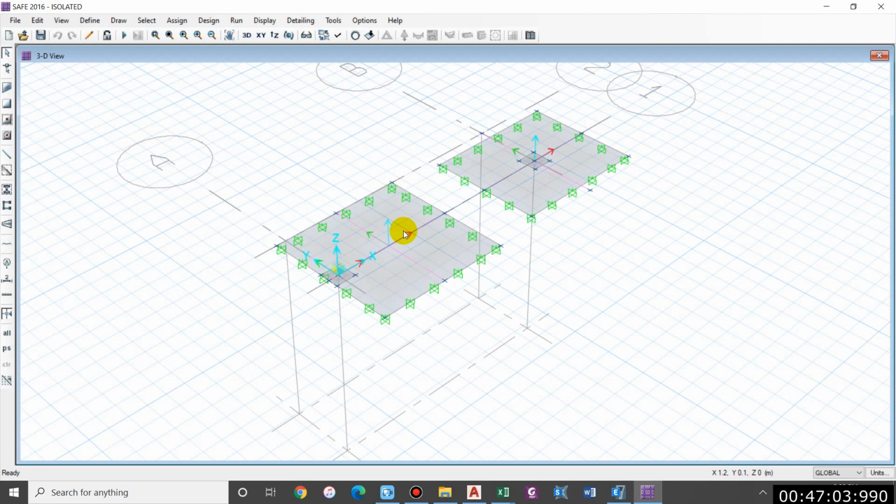Hence in such case we have to opt for other type of footing, because it will not be economical to increase the size of footing beyond certain point. So we will opt for a combined footing.